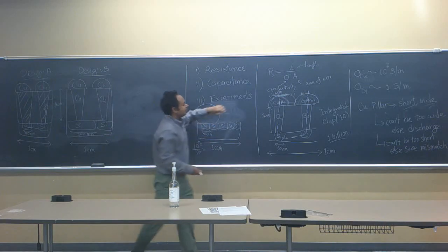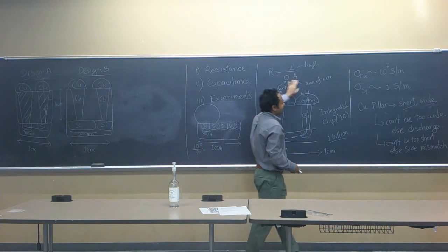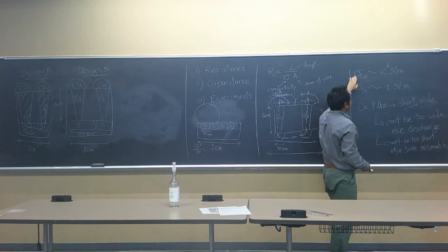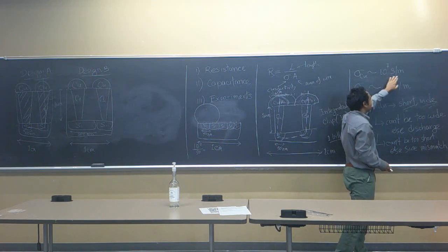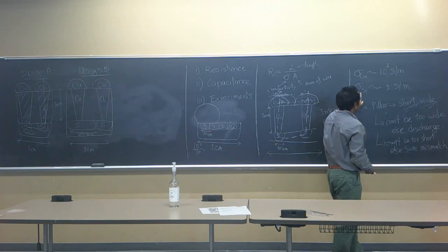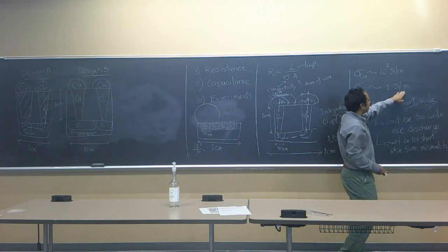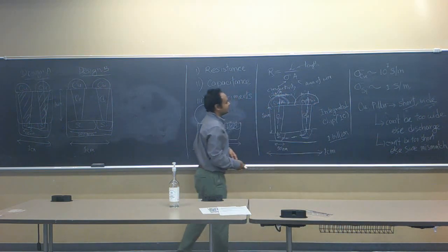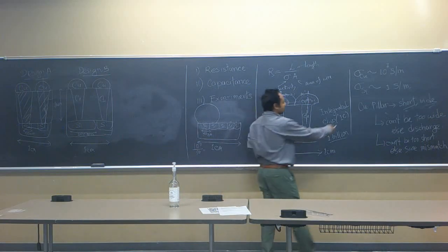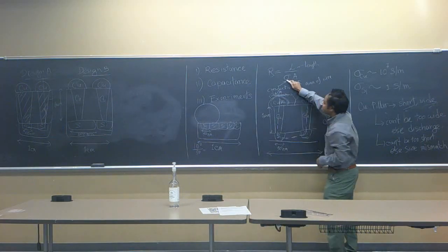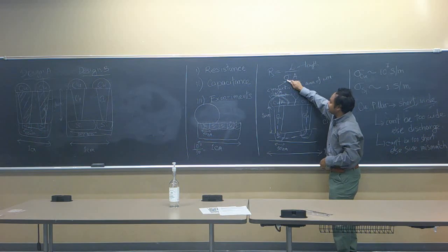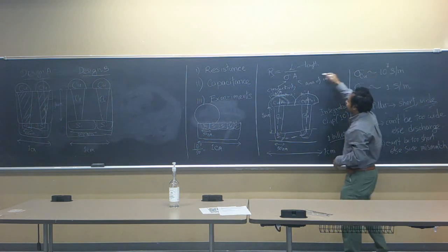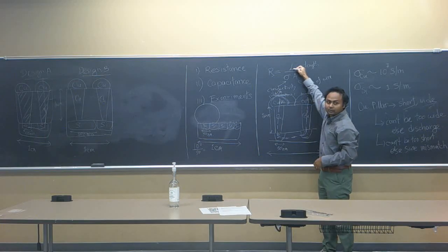Also remember that silicon has much less conductivity compared to copper. Copper has 10 to the power 7 Siemens per meter conductivity. Silicon has just 1 Siemens per meter. So there is a big margin between the conductivity of copper and the conductivity of silicon. Since the conductivity is very small, in order to make up for it, you need to make the length very, very small.